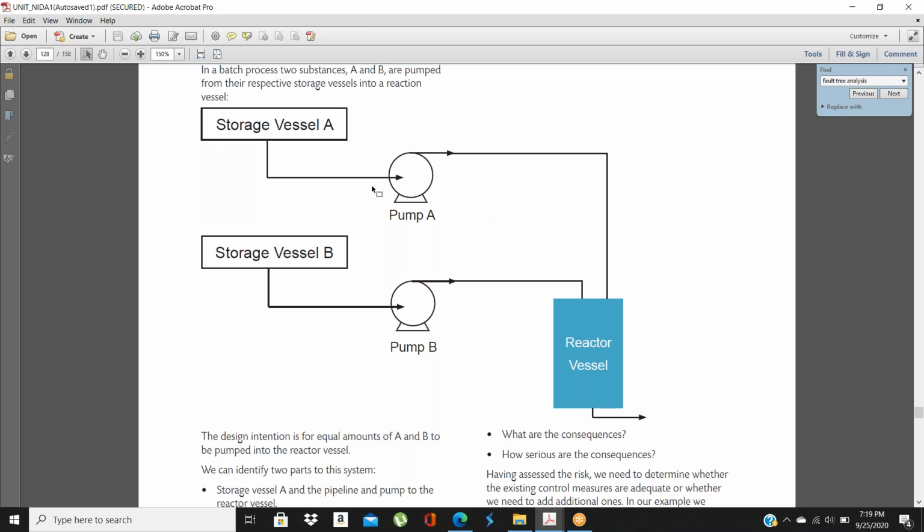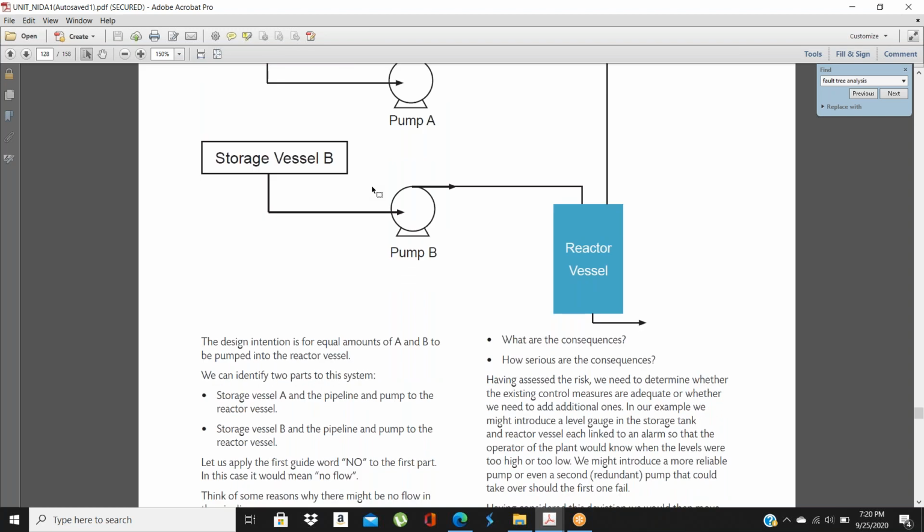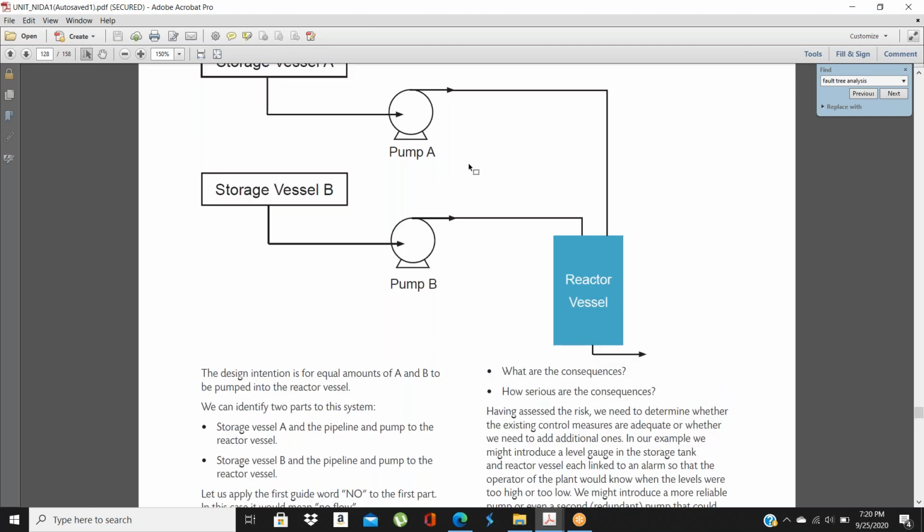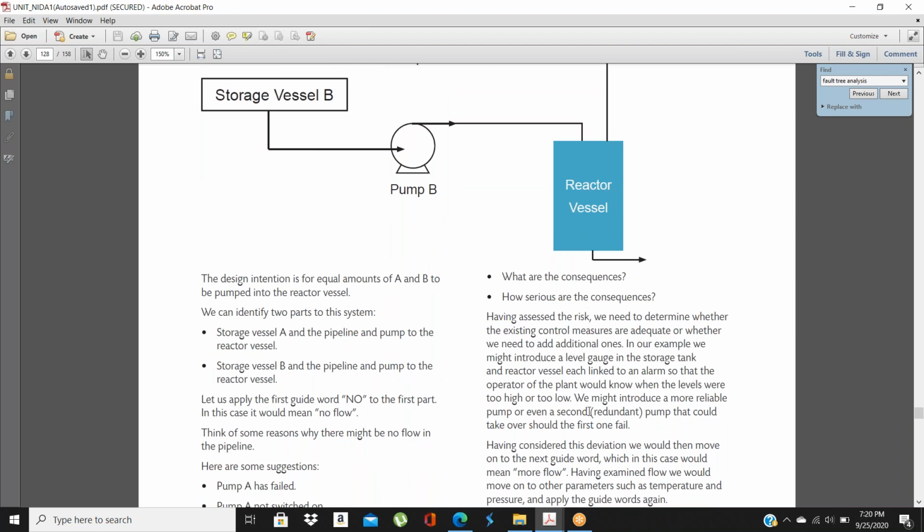applying here. Once we are installing the firefighting system, we are installing one diesel pump and one electrical pump. Let's suppose during the emergency your electrical pump is not working, so we will start the diesel pump. So two systems, this is called a fail-active or redundant system. This is called redundancy. If you install the second pump here, this word is also redundant.